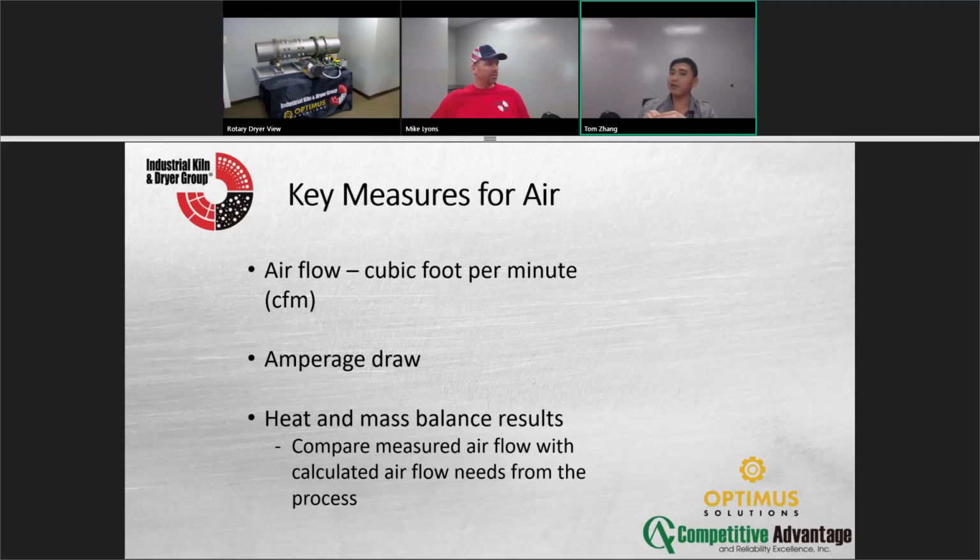Typically, you would like to have those as automated as possible because any little thing you change in the system will change your flow. It's like your house HVAC. If you close all the vents, you get more air coming out somewhere else, but then you may change the pressure drops. This is how much it can move the air. That's the other design metric that we run into. So something as simple as even a damper could cause it.